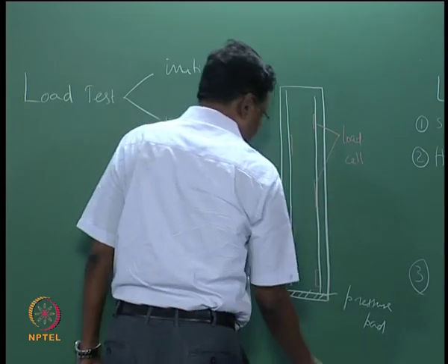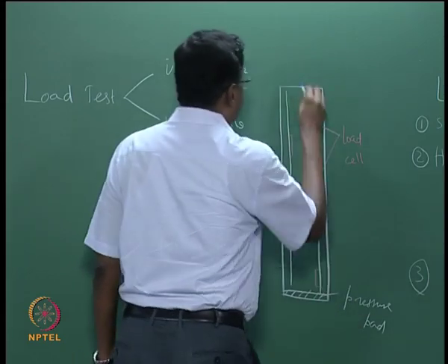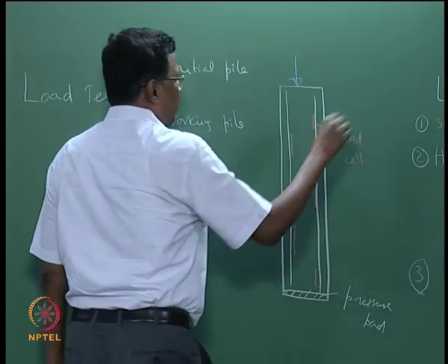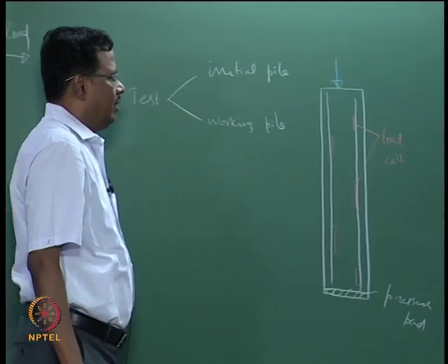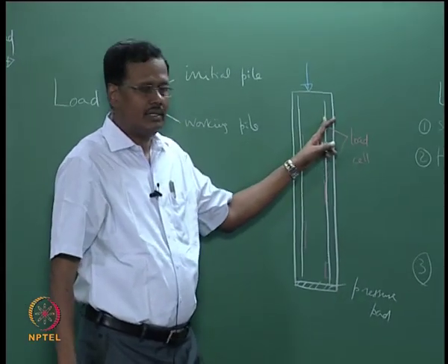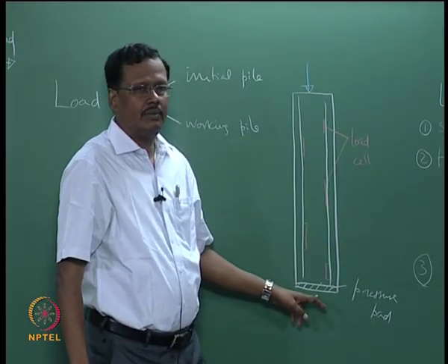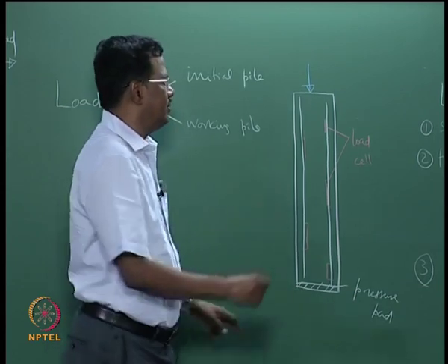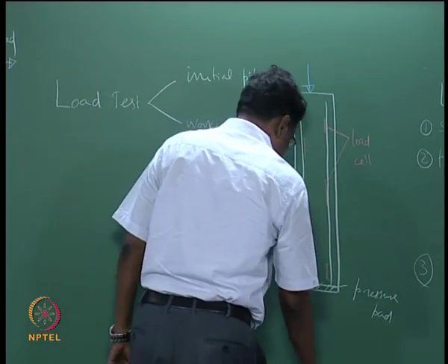Then you apply the load. So earlier we were measuring only the settlement, now you measure the load in the load cell as well as the pressure pad.